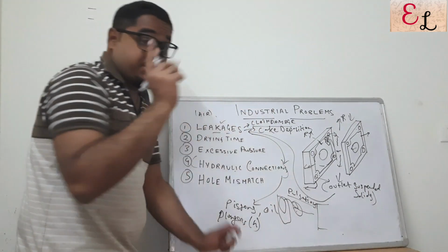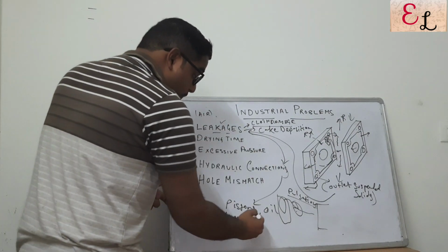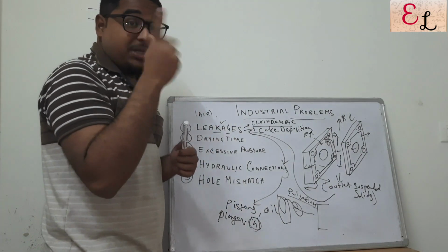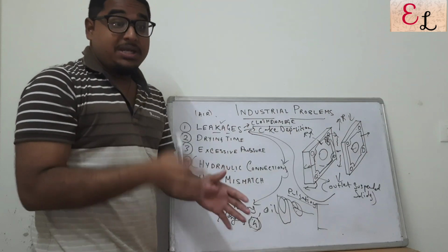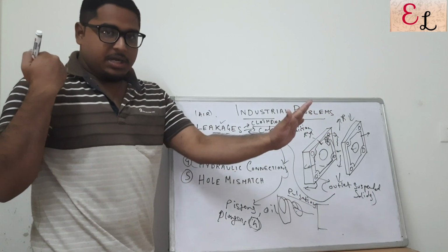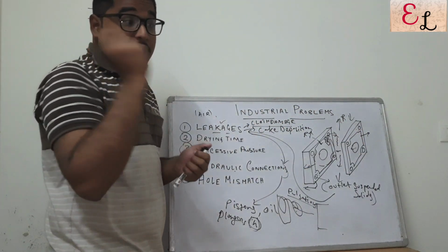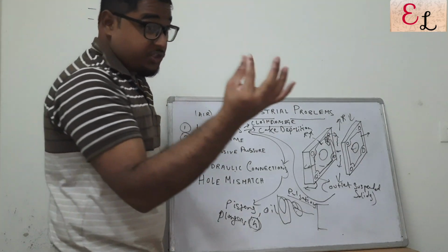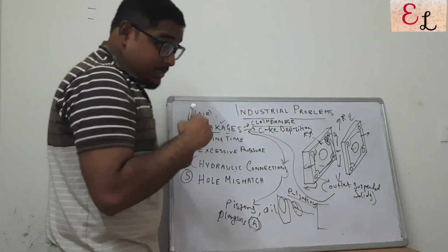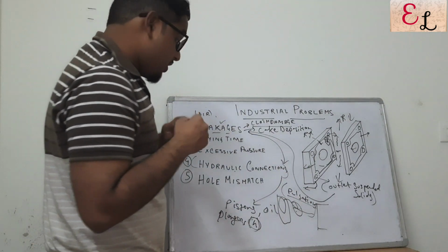If it is having pulsations, my friend, then the plunger is not performing up to the mark, which means out of the 4 plungers, at least 1 or 2 is gone, because of which you will have pulsations. If the 4 plungers are working simultaneously with each other, having a synchronic motion, when one plunger is pushing, another plunger is taking in, an alternating action, you will feel the pressure in a constant stretch and you will not feel pulsations when you touch the pipe. So to detect a hydraulic connection problem, the pulsations in the oil line are a very, very important determining factor.